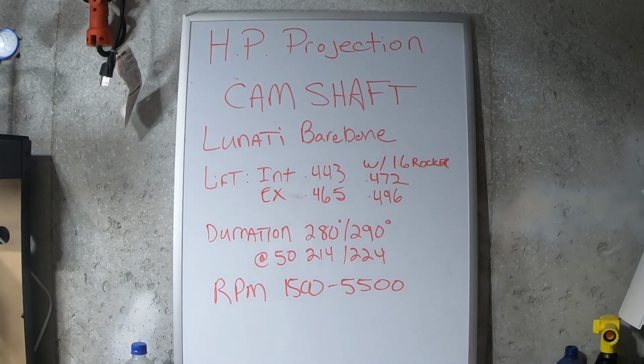I'm not going roller on this motor because that's going to be like $500 to $1,000 to do a conversion from a Gen 1 Chevy small block, which was designed with hydraulic flat tappets, to go to a full roller setup. I am going to do roller rockers, but it's going to be hydraulic lifters, just keeping it like in the factory design specs. So that's our camshaft.